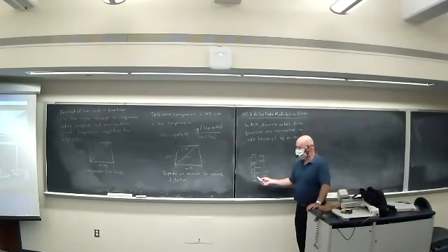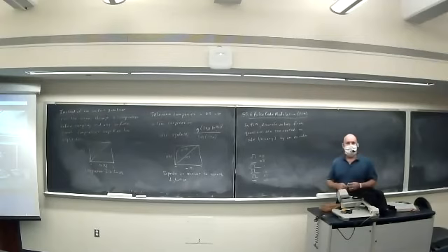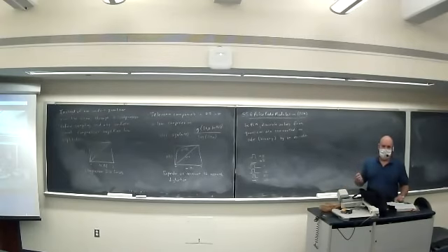When we start talking about modulation, it could be 4 different frequencies that I'm switching between instead of 2 different frequencies, which would be the binary equivalent of FM, or 4 different phase angles. Or perhaps if I used 8 different levels, I'm transmitting 3 bits in a single pulse, right? Or with 16 levels, or even in some cases, they've gone up to 256 different levels, phase angles, and amplitudes, so that you can transmit an entire byte of information in just a single pulse.